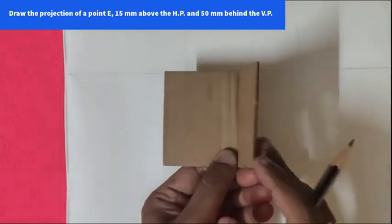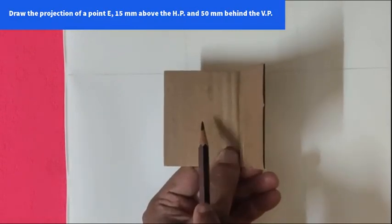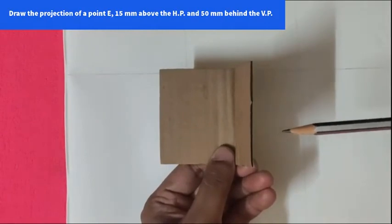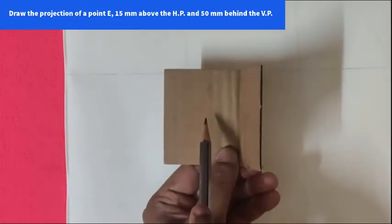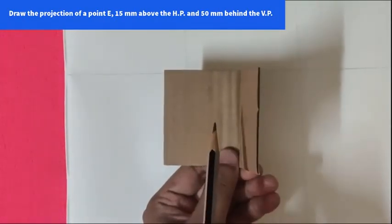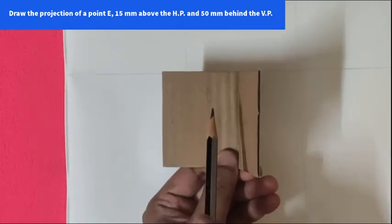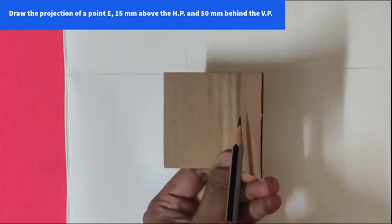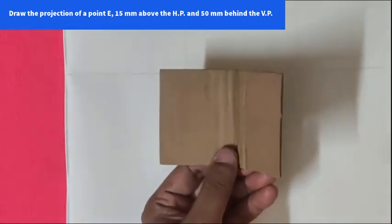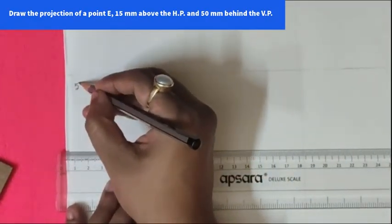So with the second quadrant, what is given? 15 mm above the HP. So when we see from this side, the front view will be projected where? In the vertical plane. The distance will be as much as given from the HP. So from the HP it has been given 15 mm. So your front view will be projected where? Above the XY line at a distance of 15 mm. So this is question number 5.